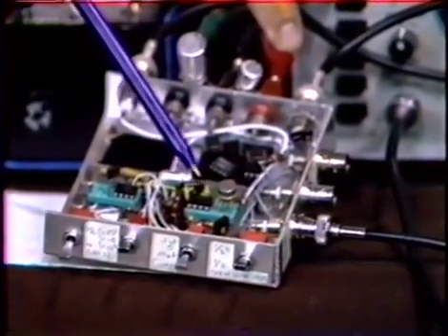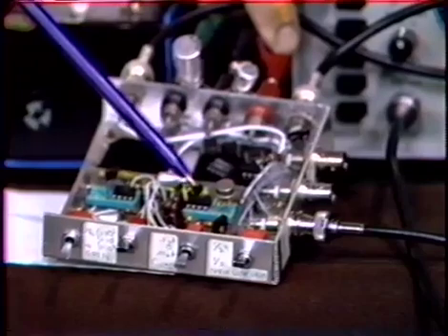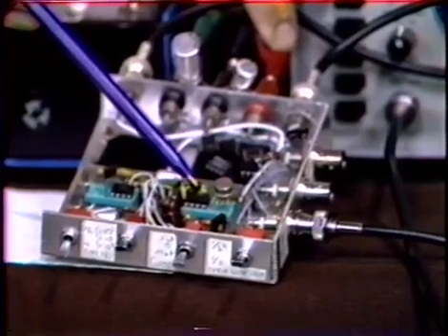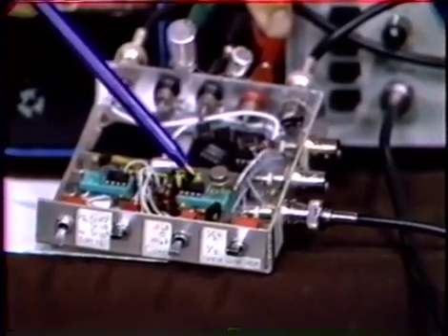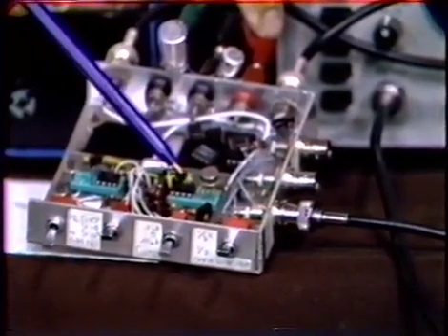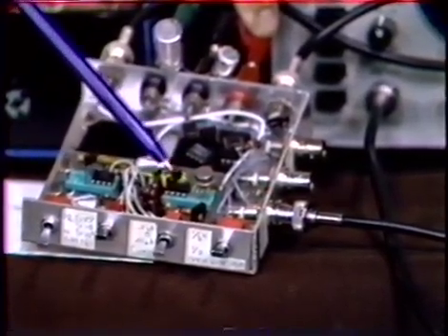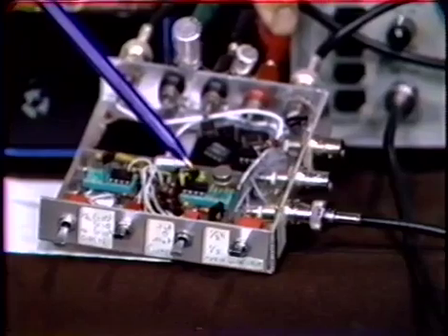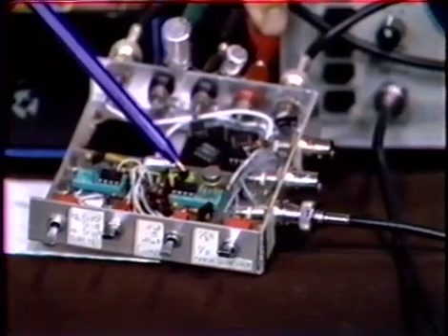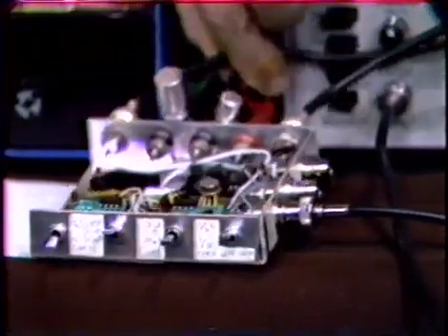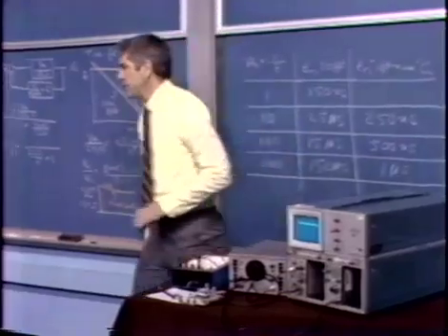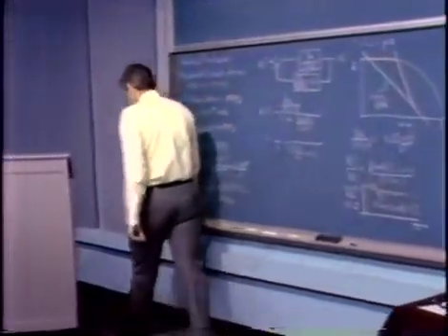We use a somewhat different configuration here. Actually, we use the amplifier connected as a unity gain inverter, and the reason is that we're able to very easily look at the error signal. Let me, if I can, look at a view graph that shows that topology.